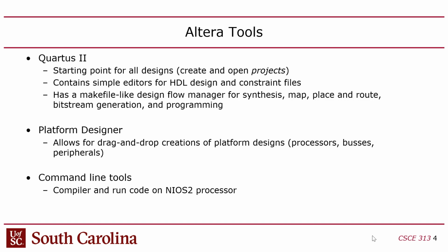What else did you use? I guess that was basically it, right? VGA. We stopped using the flash. We used to use the flash chips on there. Oh, well, the DRAM, right? You used the DRAM in 313. You might not have realized you were using DRAM, but you were, because when you loaded your software in 313, that was actually a fairly substantial block of code, because you had your code plus the BSP code. And so that wouldn't fit in on-chip memory. You had to use the off-chip memory for that, and so that's why you had to put the DRAM controller in there, right?